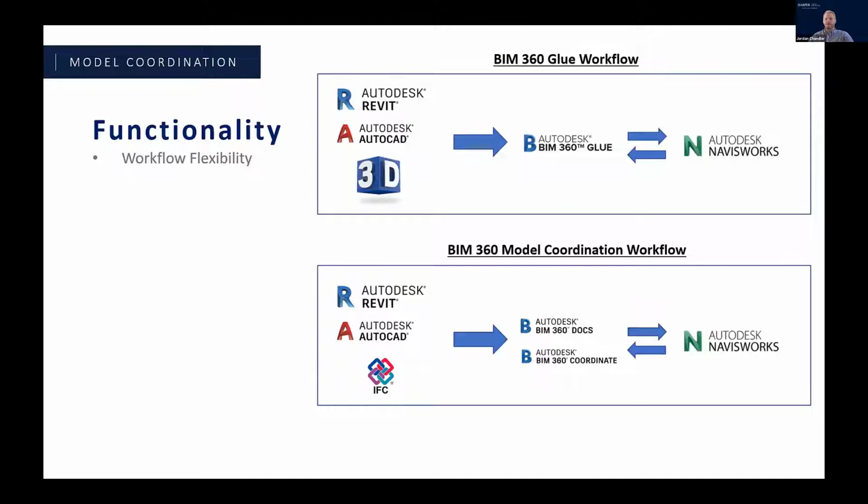If your team maybe isn't working inside of BIM 360, or you've got a different file exchange, for example, you could set up a coordination space inside of BIM 360 and simply have your collaborators upload or publish their data to that folder, similar to how they would push up to Glue, and then you can use the BIM 360 Coordinate platform to run through the coordination process. And as of recently, you can now also use Navisworks in that process to open up those views, to push issues back and forth, etc.